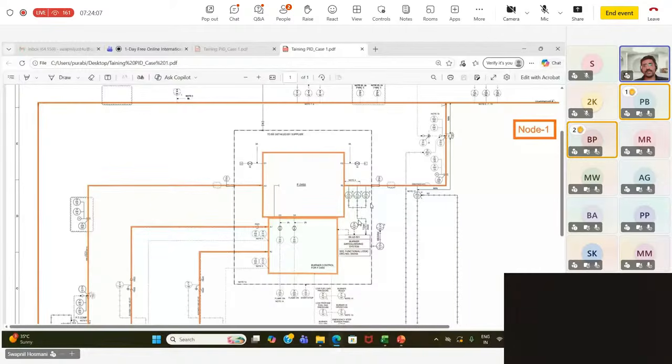It is tripping the burner management system also. Here, you can say the burner management system is the final element, but essentially they have already considered SIL3 level BMS. So when it is already high SIL integrity, we can consider this as an independent layer, because invariably it will still act as an independent loop for this safeguard. So these are three independent layers of protection in this system.